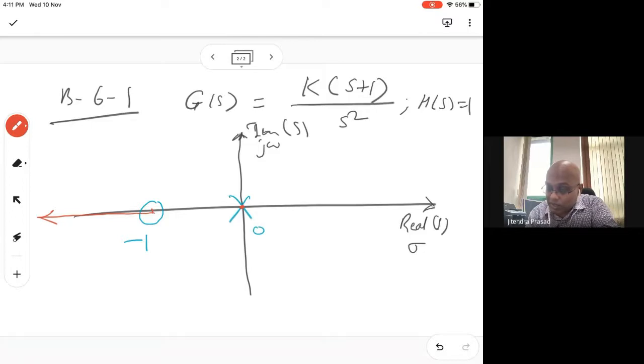Okay. So the root locus on the real axis will be like this. So here a point and here a point. But this is not sufficient. Not sufficient meaning that when you vary k, the roots of the closed loop system will move from the poles and go towards the zeros, right? So we have a zero here, and we have poles here. So there will be a connection between this and this somehow. But here it cannot go. We know that it cannot go here.